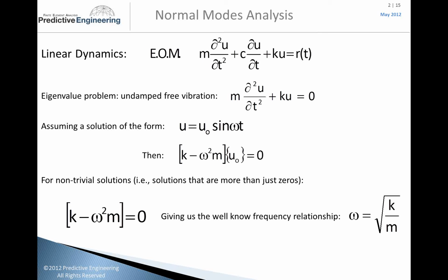And then it's just mass times acceleration plus stiffness times displacement, Ku. When we do a linear analysis, of course, there's no acceleration, and we're just doing force equals Ku. But for the eigenvalue problem, m times a plus Ku equals 0. Then you can assume a solution of the form, a displacement U max sine Wt, and that's how it all drops out.